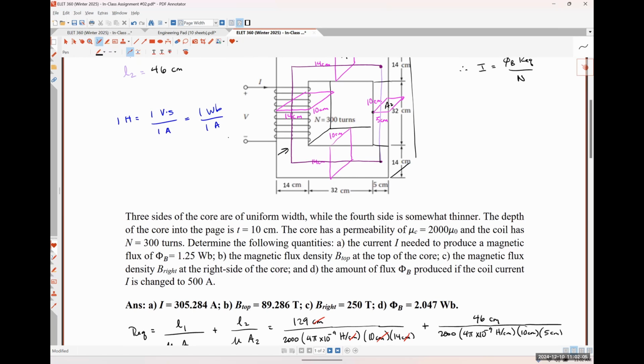So it's just the units that typically wind up getting used. I don't really have a better explanation as to why turns got tacked on there than that's what's traditional, and turns is a dimensionless quantity because it's just literally counting the number of turns. So including it or excluding it really doesn't impact the units from a dimensional aspect in any way, shape, or form. So amp turns per Weber, for whatever asinine reason, is the conventional unit of reluctance that we're going to use.